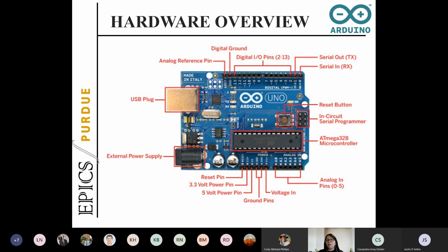So let's say you want to implement a digital thermometer where you want to measure temperature, and you have a sensor to measure temperature. This temperature is not going to be measured in ones and zeros, of course. It is going to be measured in other numbers. So that's where you can connect, and your Arduino can get that information from your sensor. That's how this analog input works.